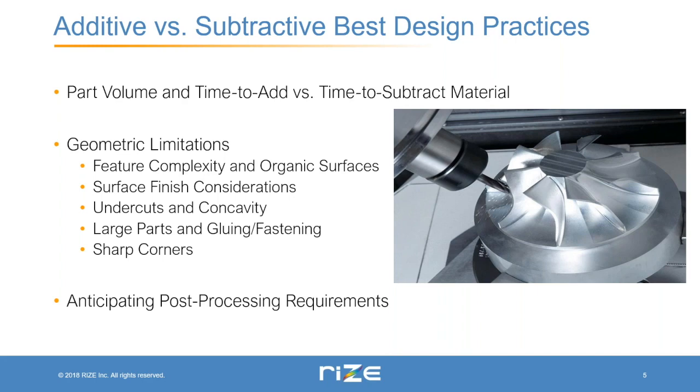if you have a large volume part, it's often difficult to produce it in a reasonable amount of time using additive manufacturing, whereas that doesn't have much of an effect on subtractive manufacturing. So if you have designed a part for subtractive manufacturing, which has a lot of extra material attached to it, or conforms to the shape of the stock material, then preparing it for additive should probably involve removing some of that excess material and slimming it down to just the necessary portions.